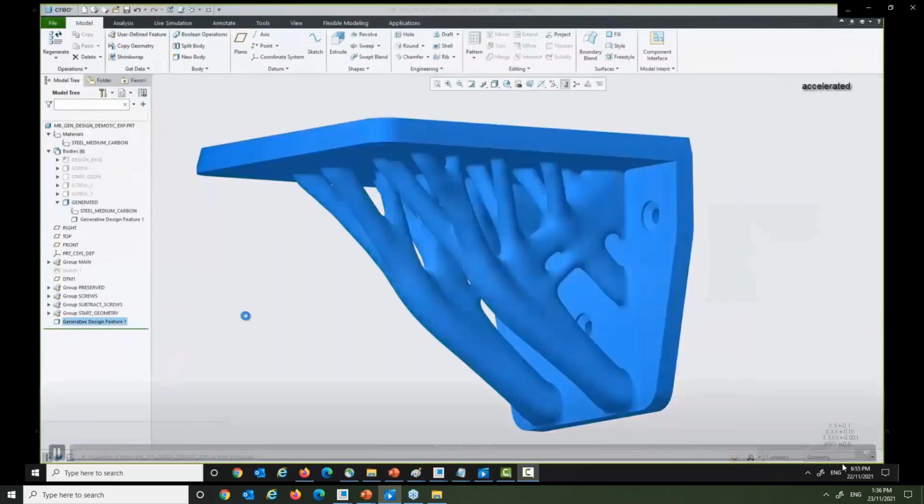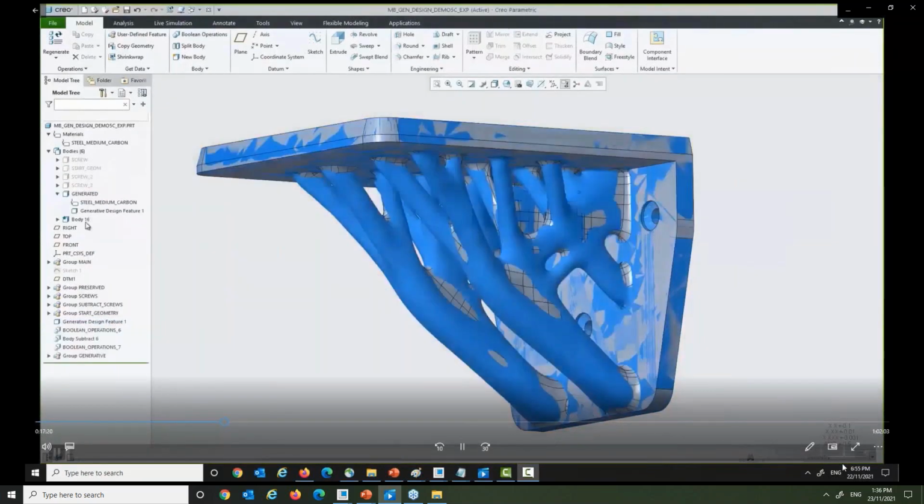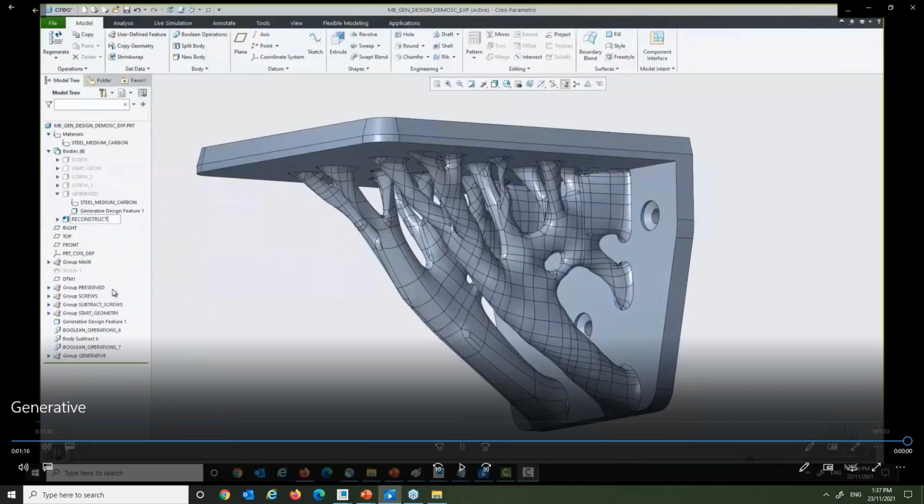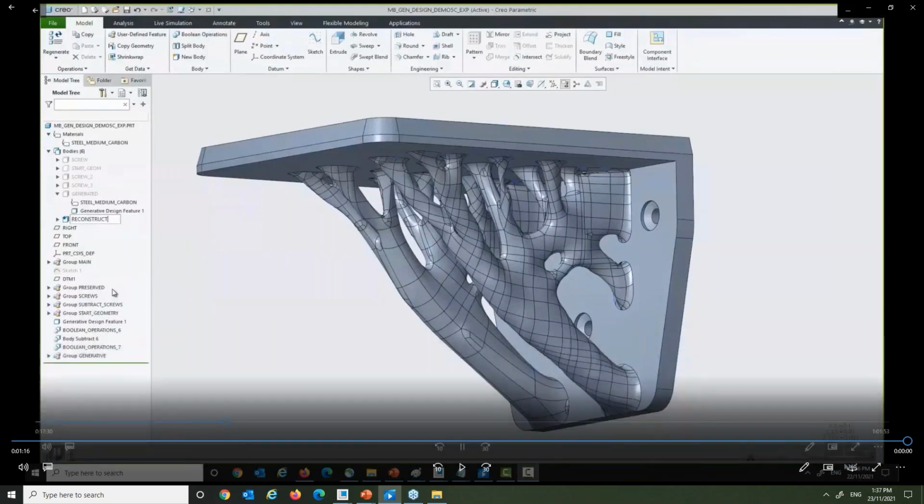If you would like to continue and create a B-spline representation, converting that into surfaces, you can go ahead and do that. Again, at that point, you have the option to make it a separate body, merge bodies, and use the Boolean operation to merge with your existing shape and so on. Again, this applies the whole concept of multi-body in different applications of Creo.